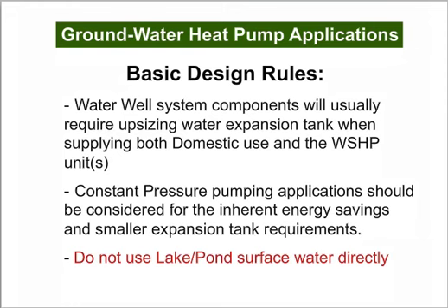Constant pressure systems, or CP systems. Basically, that's a variable speed pump and an inverter. These are very nice. They've been around for a number of years, showing very, very good energy savings as well as good performance and longevity. And the price is getting fairly competitive for residential water well pumping. You need much, much smaller expansion tanks. You're going to see that coming up.